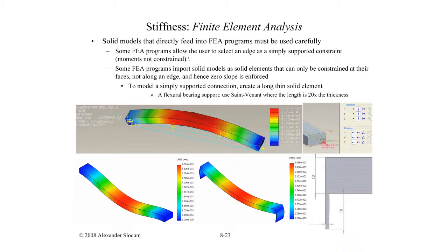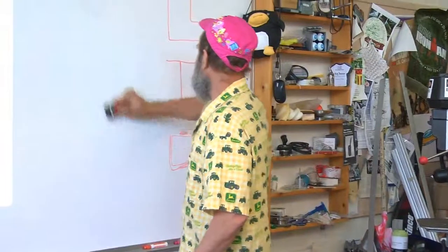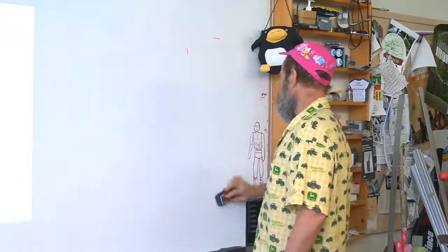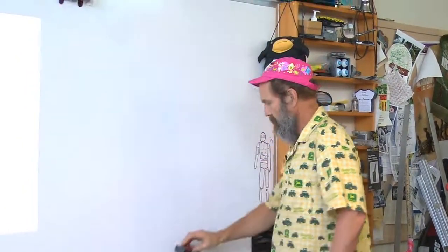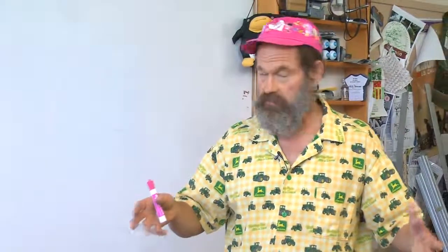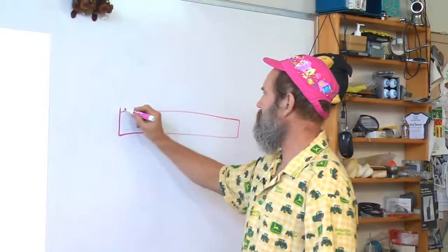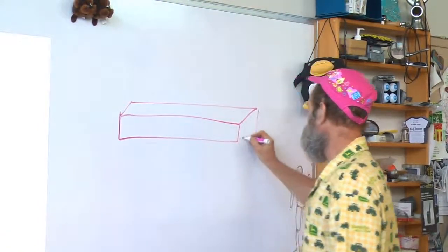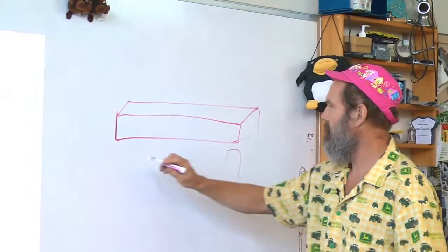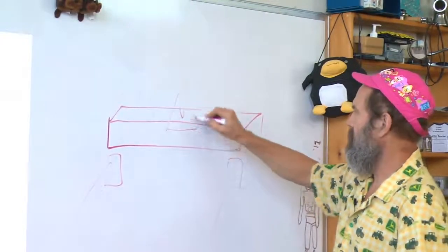Another very important thing to remember when you're doing finite element analysis, when you get to it, is the following. A lot of machines are designed using solids in the solid modeler, and then they use the auto-meshing programs to create the mesh of finite elements upon which the analysis is performed. If you were to take just a beam from a solid model, there's a beam in my machine. Let's say the machine is supported by other parts. It's being loaded by some loads on a carriage.